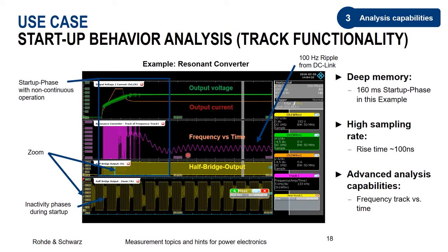This is where the converter is in kind of a steady state, and the remaining thing happening in the steady state, in that case, is only the remaining ripple of the DC link, which has to be compensated by the converter, because if the DC link voltage gets lower, then the converter has to transfer more energy, or actually has the same energy, but the transfer of power has to be higher in order to compensate for the lower voltage. That's basically the thing.